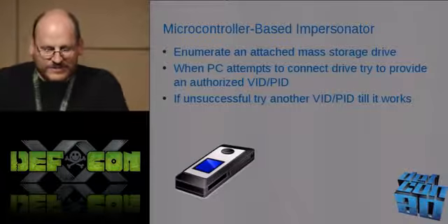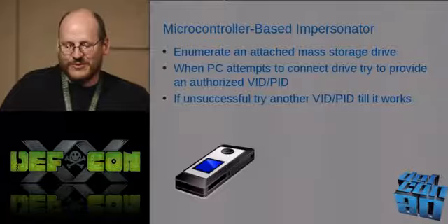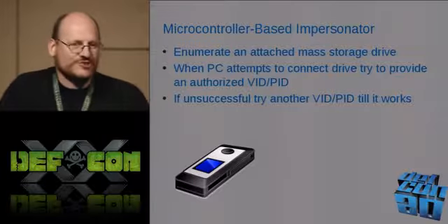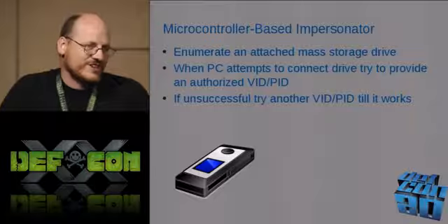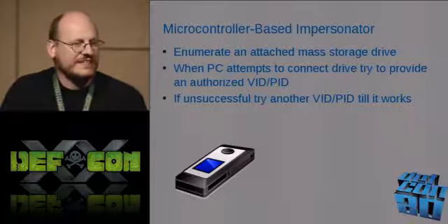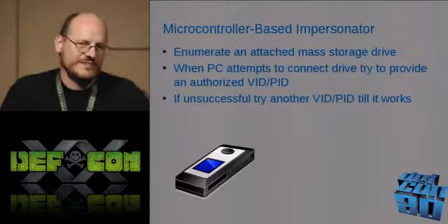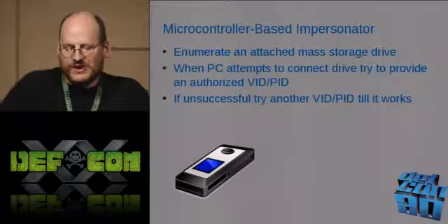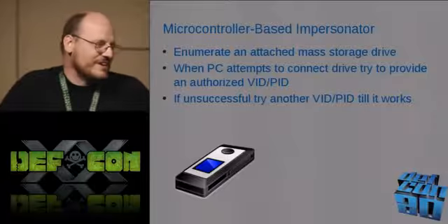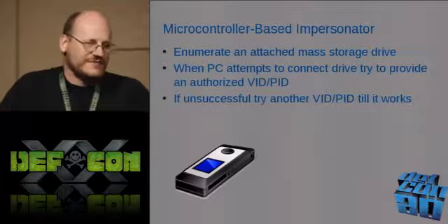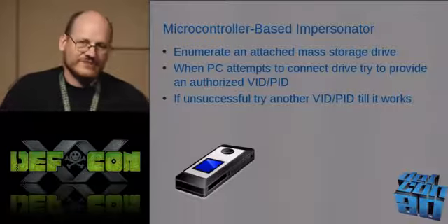All right, so how does this microcontroller-based impersonator work anyway? What it does is it allows you to insert your flash drive, and it enumerates it. And then when you plug this device into the PC, it says, oh, I see there's a new device. Let me enumerate it, and it tries to get an authorized vid-PID combination. Right? If it's not successful, it tries the next one.